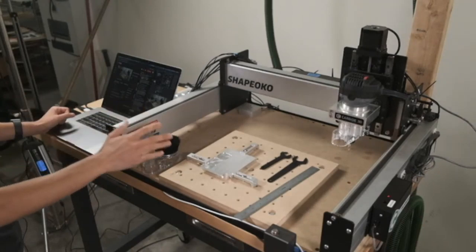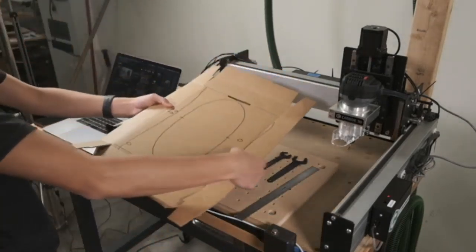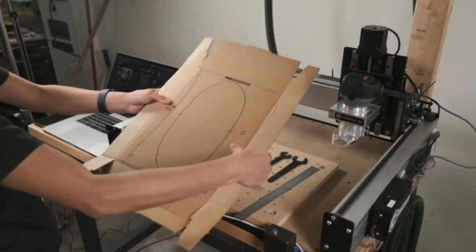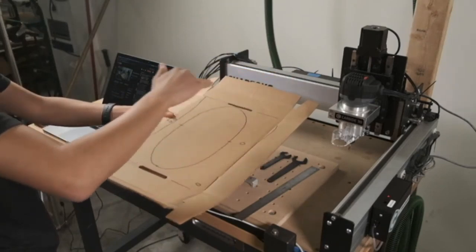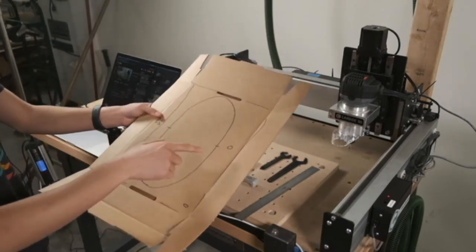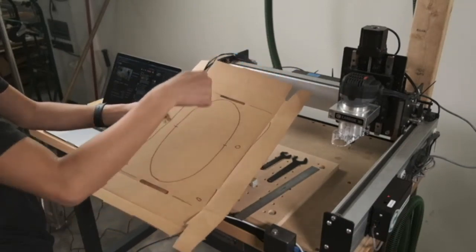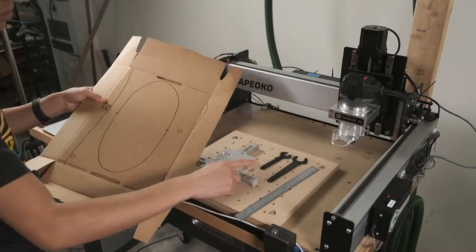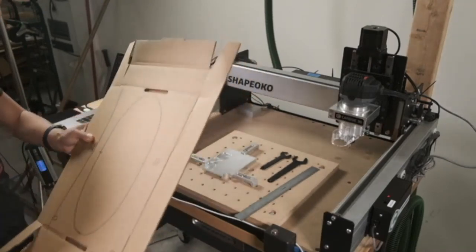The other thing is, if you have a, pretend this is wood, it might be bowed, it might be cupped, it might be warped. So when you flip it, one corner might be lower than the other, and you might get some subtle differences in how your shapes line up or the depth of cut. But if you set the reference to your wasteboard, at least you'll know you'll cut all the way through whatever it is you're machining.